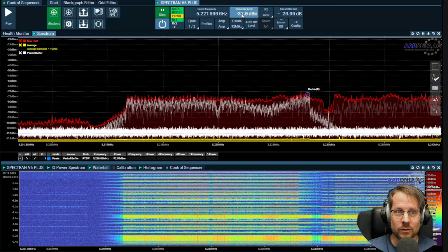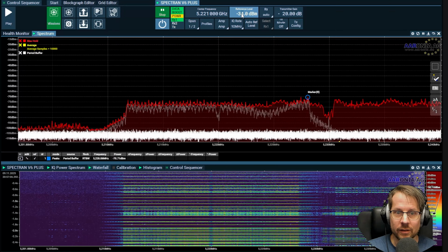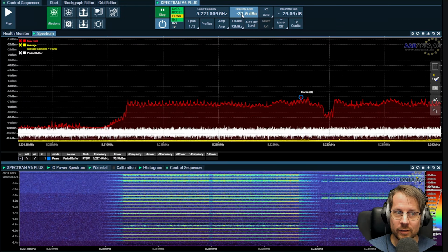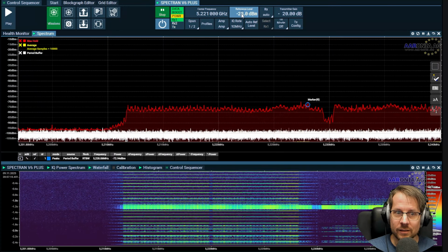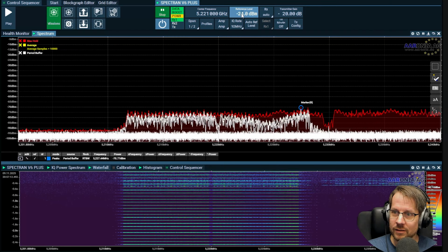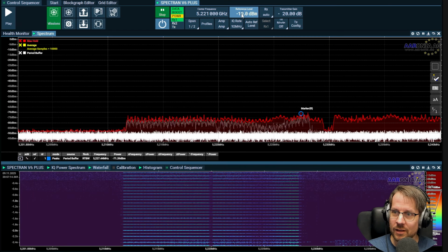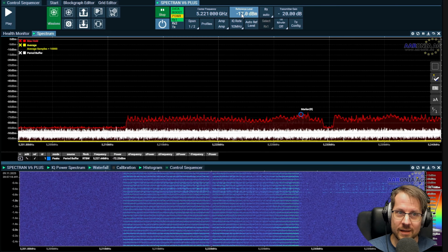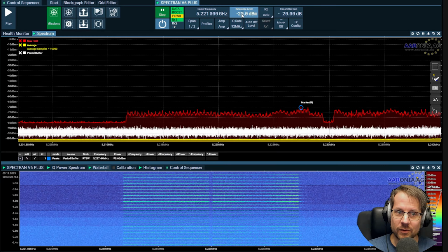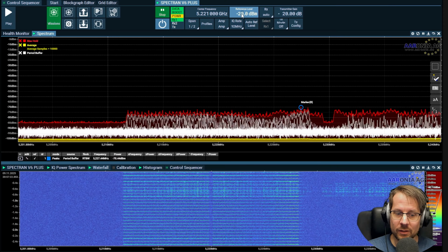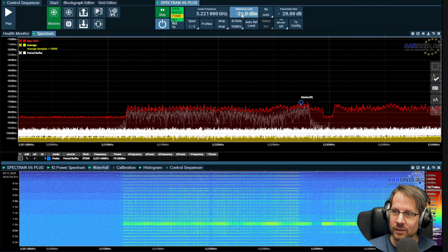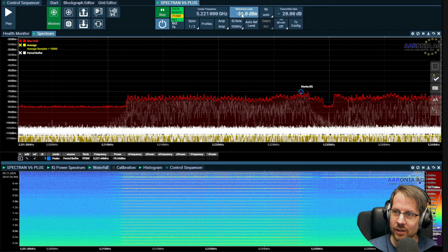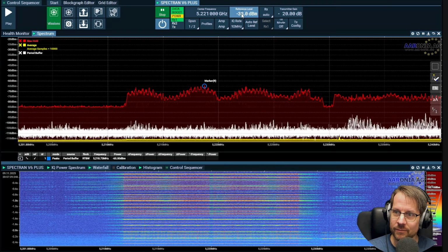So that is that. And I can also use the internal attenuation, right? So if I set it lower, you see I'm attenuating the signal more and more. This is the reference level, the internal digital step attenuator that I'm tweaking here. So if I start at minus 20, for example, and I lower it down, lower it up, right? Then I get better receive sensitivity, right?